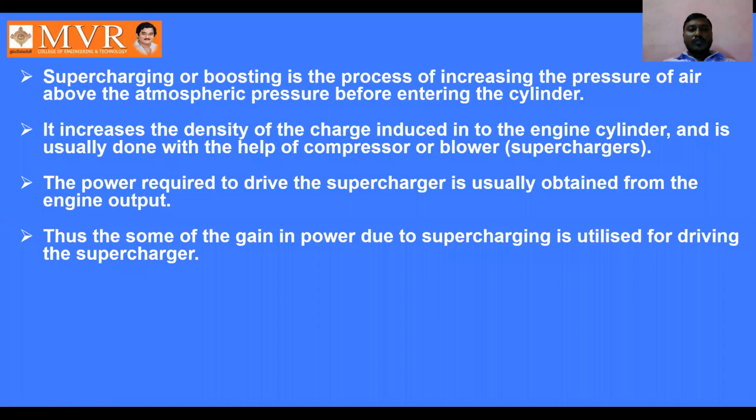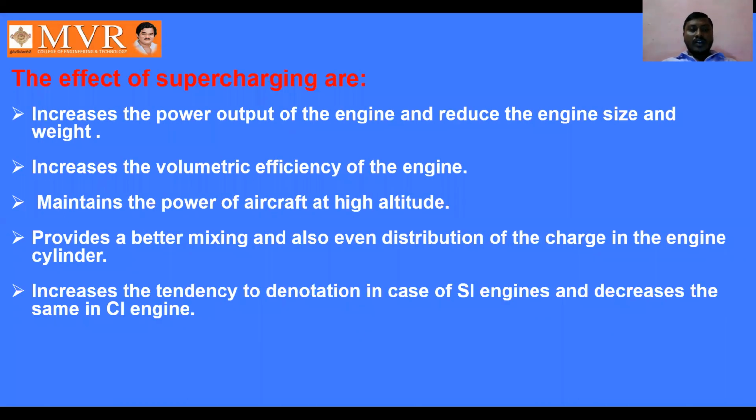These are the types of superchargers we are using here, and these are the effects of supercharging: the power output of the engine increases, the engine size is reduced, and the weight of the supercharger is reduced. It increases the volumetric efficiency of the engine and maintains the power of aircraft at high altitudes.